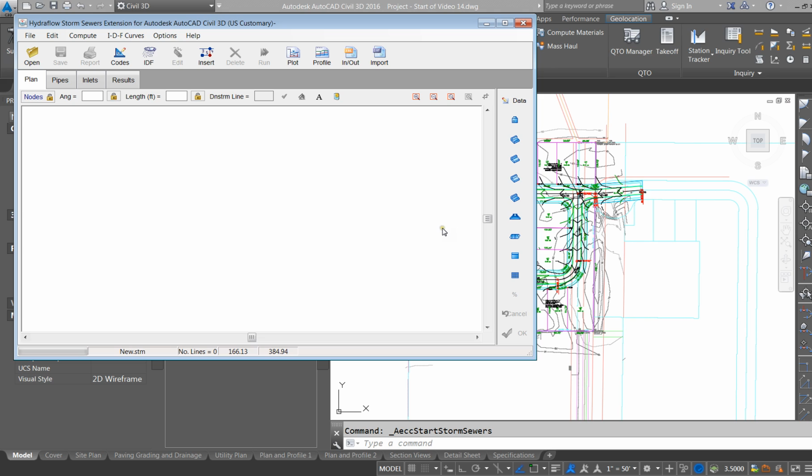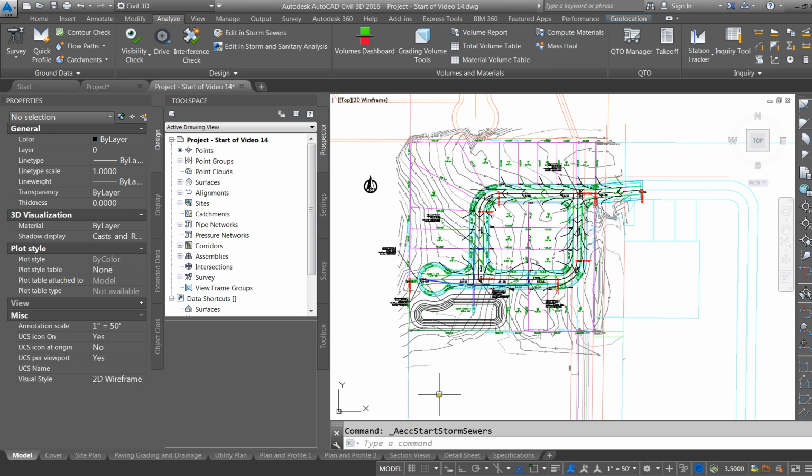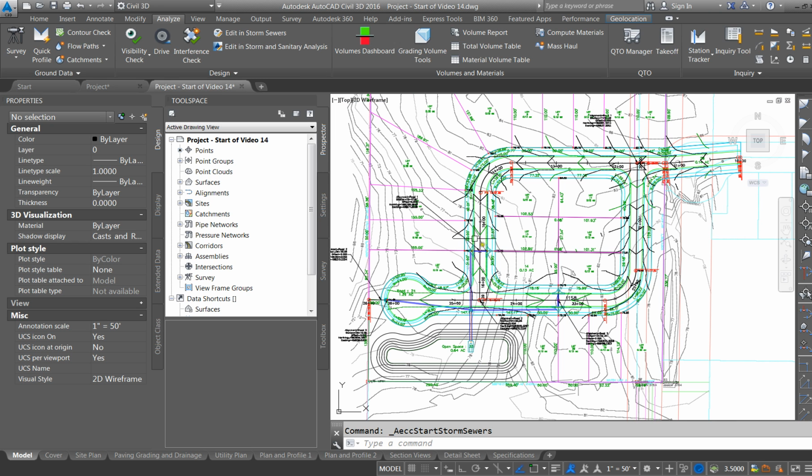So I'm going to move forward on just what a subdivision set of plans requires. And subdivision plans, I mean, any plan when you're developing any type of land, requires an engineer to design the storm pipes because we don't want anything to flood. So TR55 or a program like it requires us to design the detention basin. The TR55 requires curve numbers, time of concentration, and stage storage of the pond. Whereas the rational method only requires a time of concentration, a runoff coefficient, and an intensity factor based on the runoff coefficient and the drainage area.